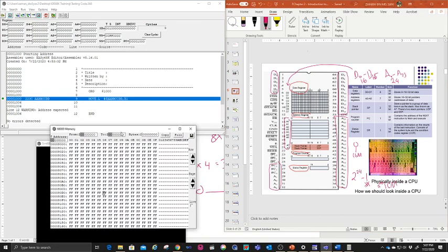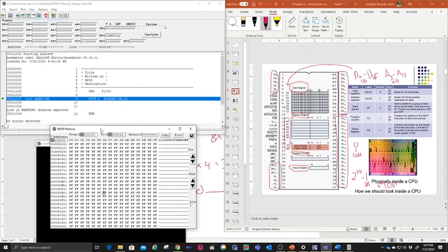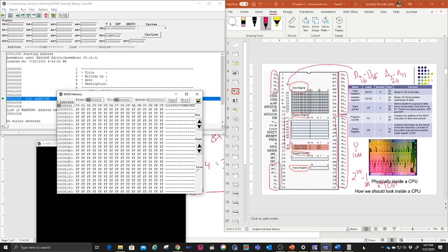So here, when you view the memory, it will show you the contents of the memory outside here, from 0 to FFFF. You can start from the address 000. By default, all the values here are all F. And the final one will be FFFFF, right? So the final one will be here. This is the last location of your memory. Each memory location is only 8-bit.